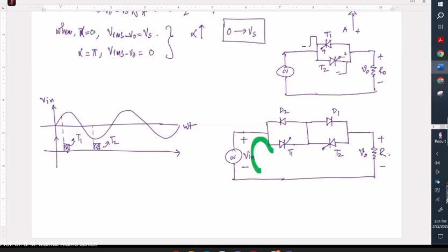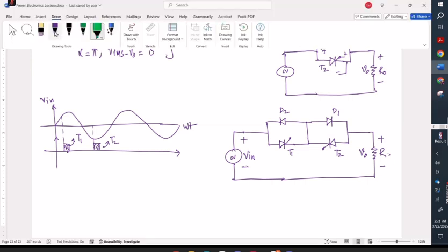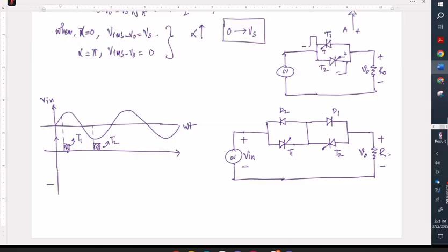Yes, sir. So the thyristor will operate now, and the current will flow like this. It will activate as we were seeing in the previous cases. So here you will have the positive portion, and it will be working like this. Now, as soon as it goes negative, although this thyristor is not turning off because the current is flowing, this diode will be turned off.